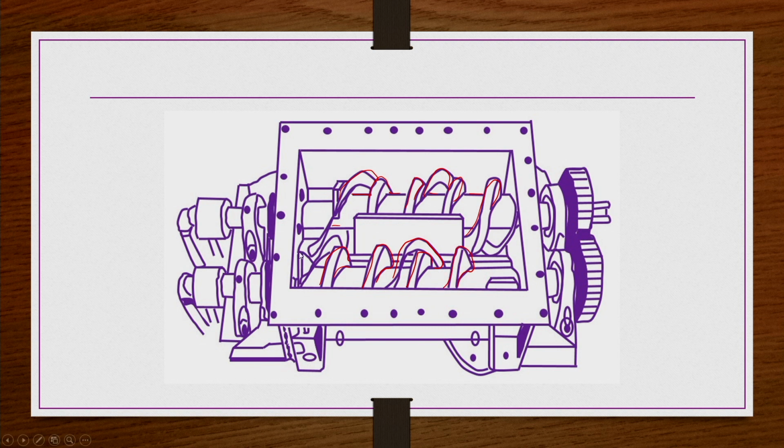So the material, let us say, comes in from this side. Because both of these rotate, the blades carry forward this material, they may take it in this particular direction. So it is taken forward as well as moved through the center, so that efficient mixing can take place, and then it is collected from the other end as product. This is the basic, very simple principle, but the problem with this kind of mixer granulator is that the throughput is very low.